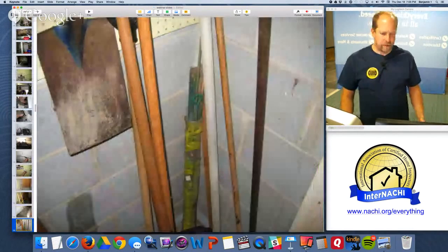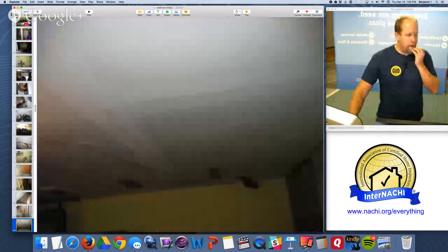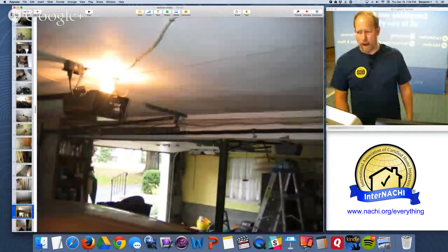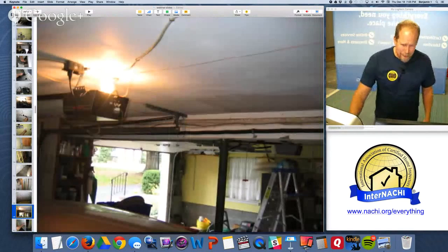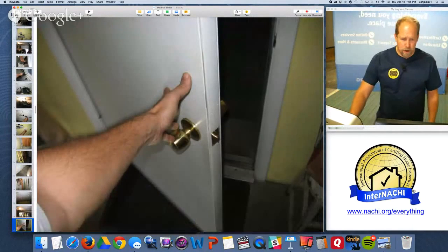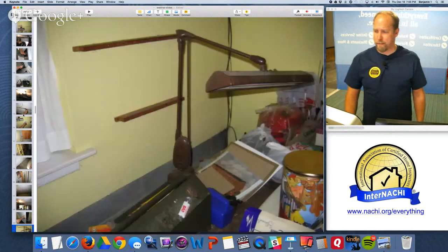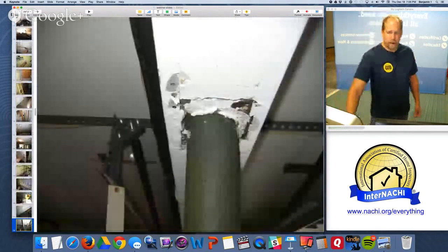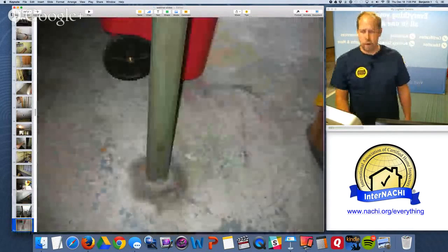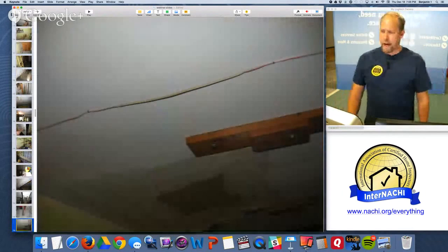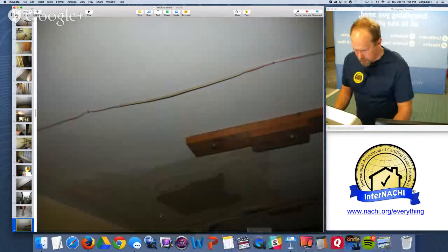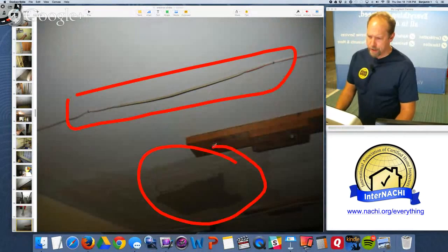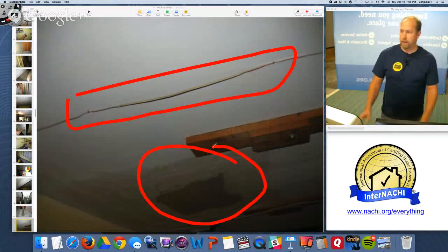So watch for retrofits. I'm taking a look at the structure of the garage. A lot of improper wiring, a lot of wires just hanging with a staple and some duct tape and twisted around. The fire door is not to modern code, but at least has some metal on it. So I'm identifying the firewall. I take a look at the main beam, the center beam, and the post, how it goes into the concrete. And we also have a patch here, typically a bathroom above the garage ceiling.